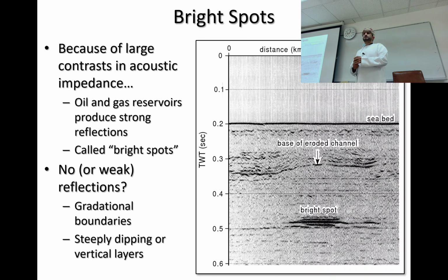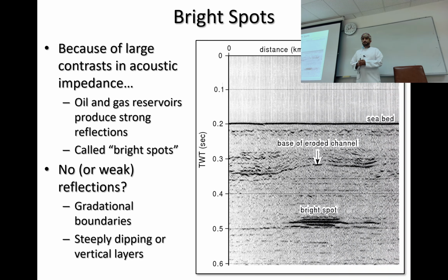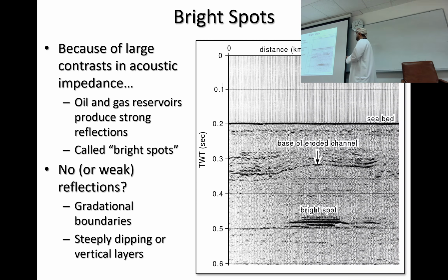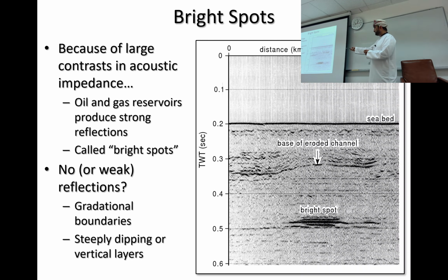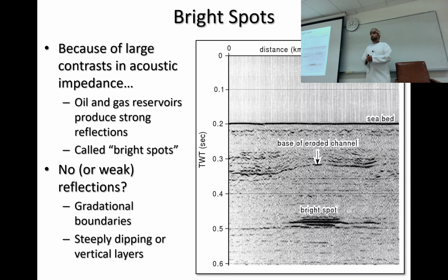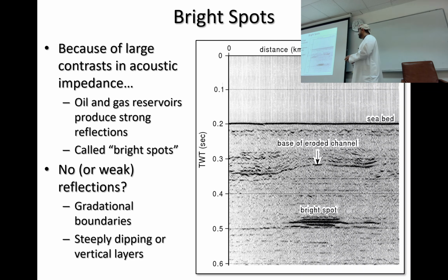This is the seabed. The reason being the contrast between the acoustic impedance of the water column and the underlying sediment is so large, it will produce large amplitudes. The reflection is so strong. So we'll get strong reflectors.